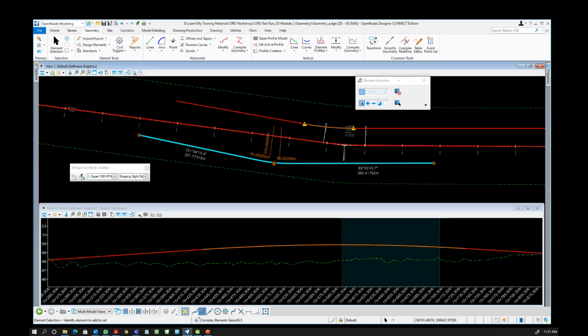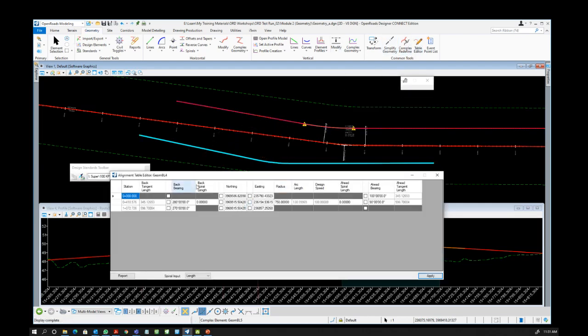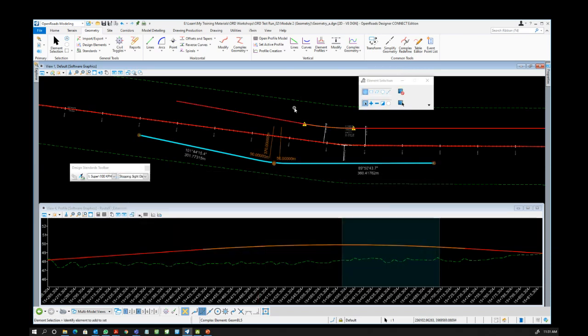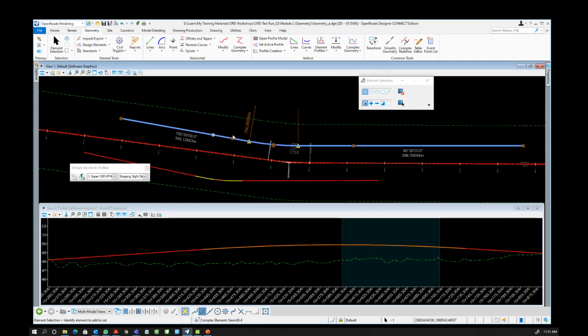Of course, you can redo. Control R, you can redo. Any method to edit a complex horizontal alignment if changes in part of the alignment are required instead of rebuilding the alignment? Yes, as I said, you can use the table editor, or if you want to use the usual drop or explode tool to put it back to its original setting, being line, curve, or arc. You have many tools to do the modification.